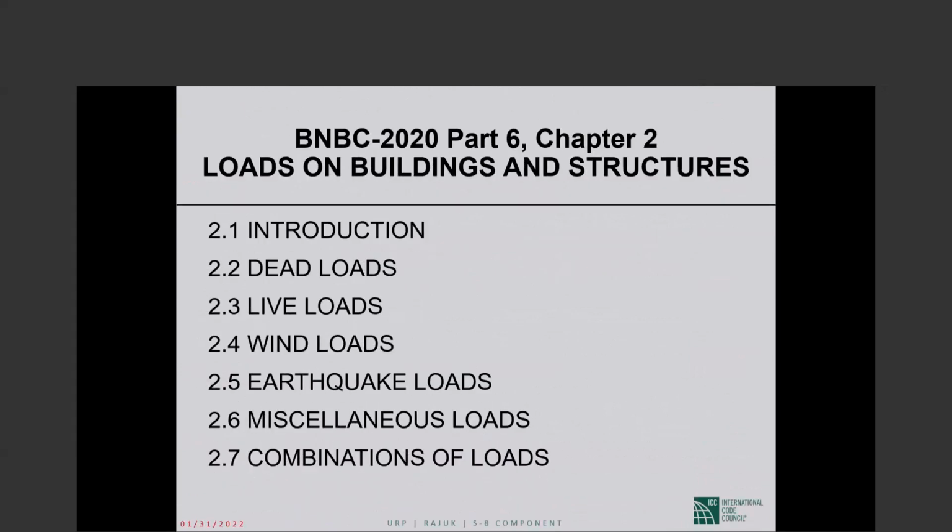Okay. So that brings us to part 6, chapter 2, where the loads actually are given. This chapter has an introductory section, then it talks about dead loads, live loads, wind loads, earthquake loads, miscellaneous loads. Under that, there are quite a few things. And then combinations of loads. You design your structure for combinations of loads, not for just one load.